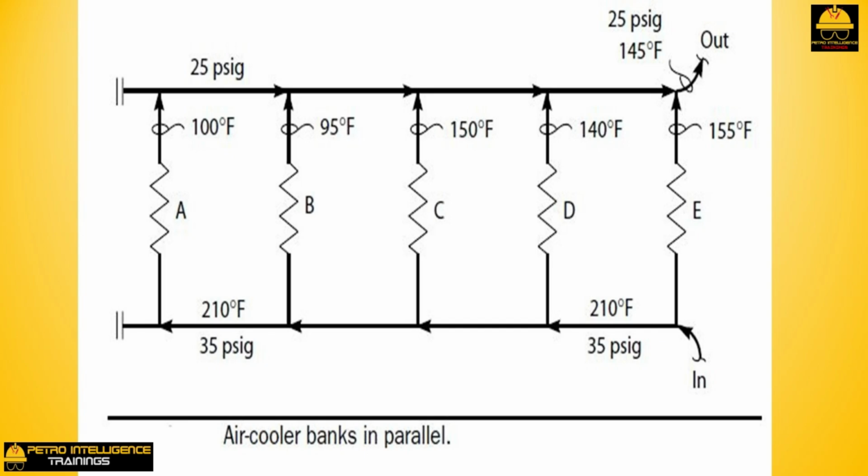The best way to handle the non-symmetrical flow problem described previously is to make the pressure drops in both the inlet and outlet tube bundle headers very small, as compared to the bundle pressure drop itself. Many of my clients add additional tube bundles in parallel with existing air coolers. This helps at first, but they find that the long-term benefits are quite disappointing because of high pressure drop in the new header lines. Slug washing individual tube bundles with steam condensate also helps. Washings for 20 minutes once a week are often sufficient.